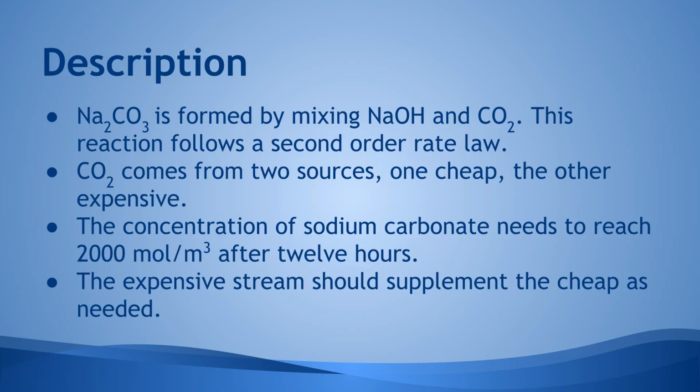The idea behind our project is that we were wanting to minimize the use of the Praxair trailer but still meet the required specifications in order to produce the sodium carbonate necessary. One interesting design challenge that we had, and this is based off a real-life example, is that the measurement device for our reactor is an operator that has a stick with a cup on the end who goes out there, takes a sample, and then titrates it, and then enters that information into the computer, and then our controller adjusts based off that information. So we have a very large time delay from that.